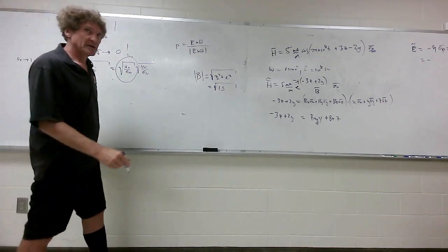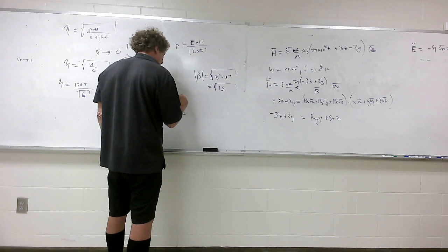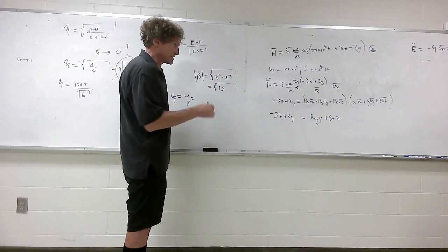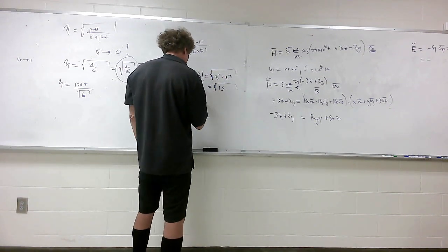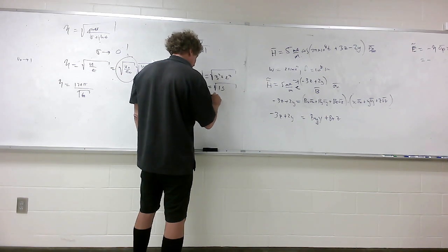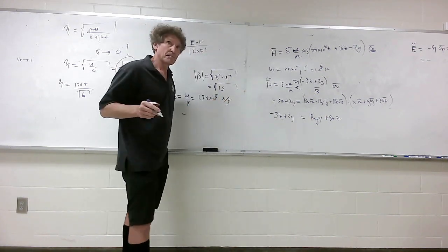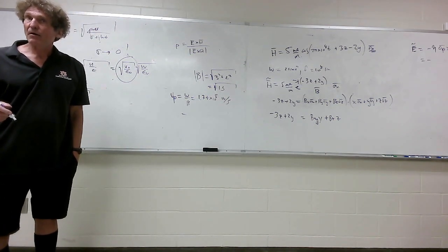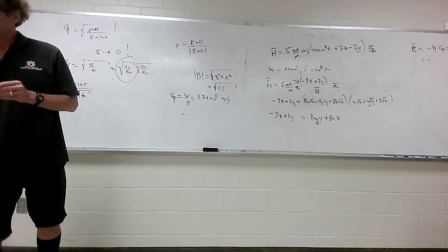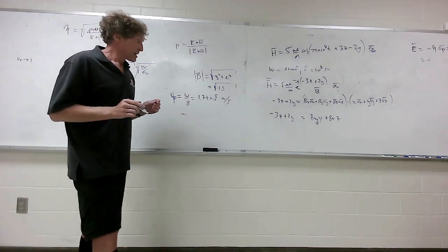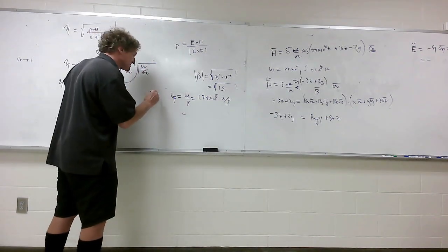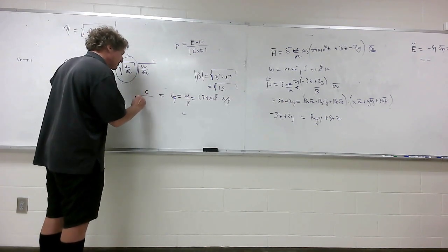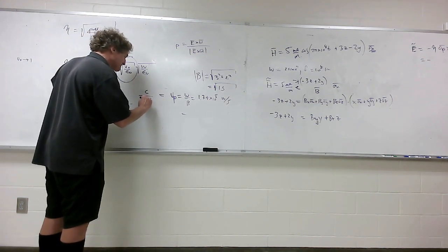I erased the thing down here. I said the phase velocity was equal to omega over beta, and we calculated it after I adjusted that to be, was it 1.74 times 10 to the 8th meters per second? Is that right? Yeah. Y'all remember this, class? Now, it's lossless, and sigma is 0, right? That means phase velocity, if it's lossless and sigma is 0 and it's non-magnetic, can be rendered as c over the square root of epsilon relative.